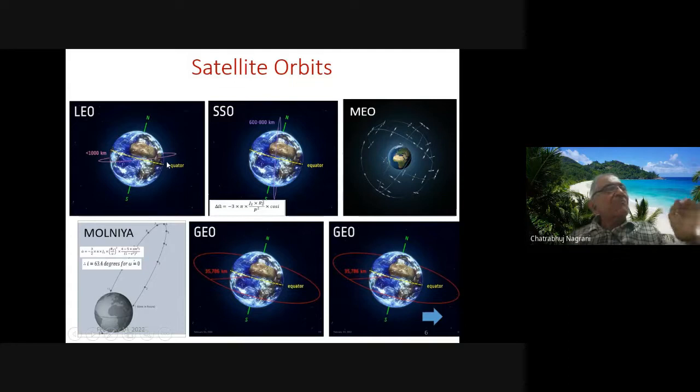As long as I am not giving any condition on the orbit, it can be in any plane. It can make any inclination, it can be even 0 inclination, or it can be 90 degree, 97 degree, all the way. That is called low Earth orbit. Then you define its inclination and orbit height. If it is an elliptical orbit, you have to define both apogee and perigee. If it is a circular orbit, you define only the radius.